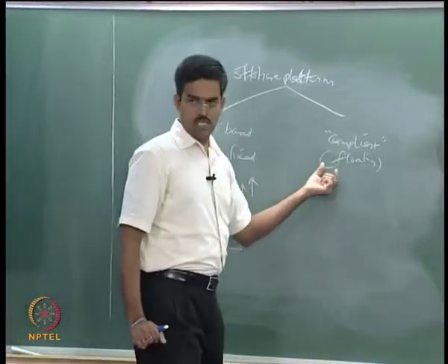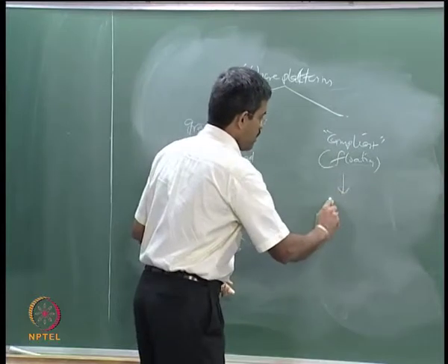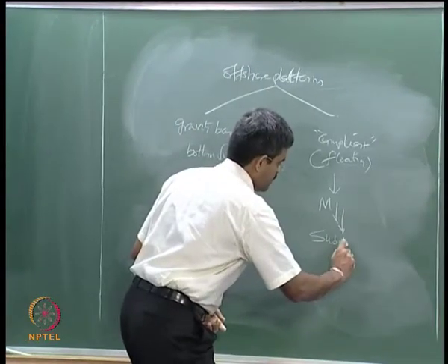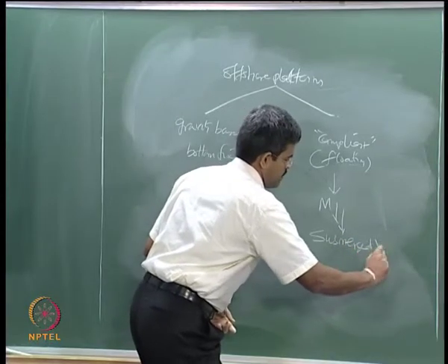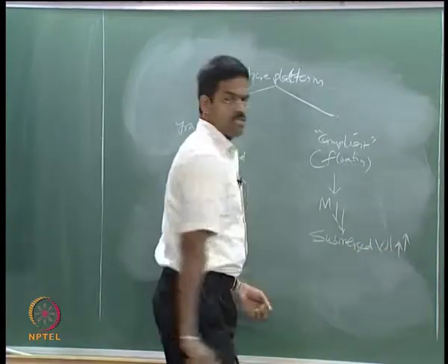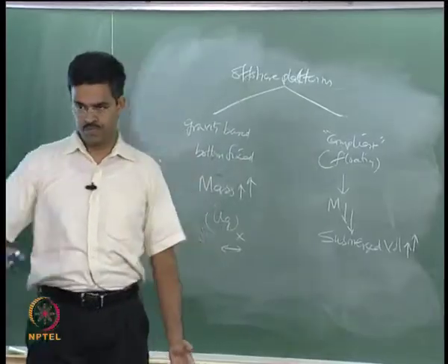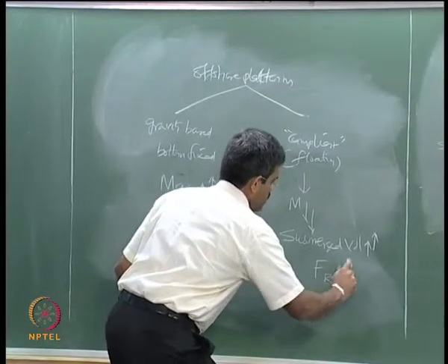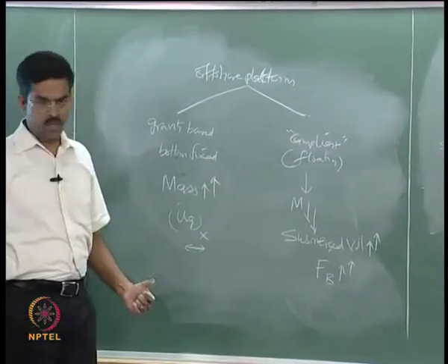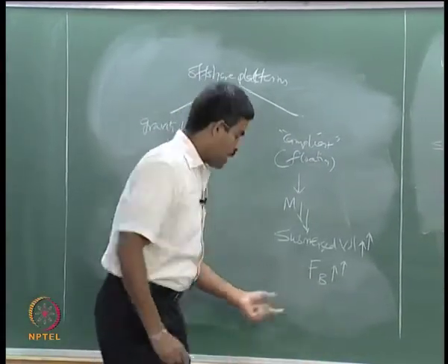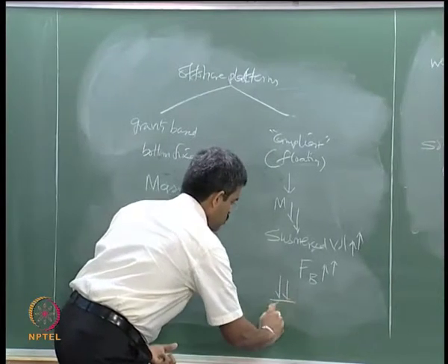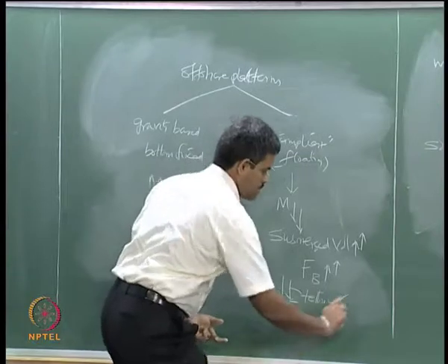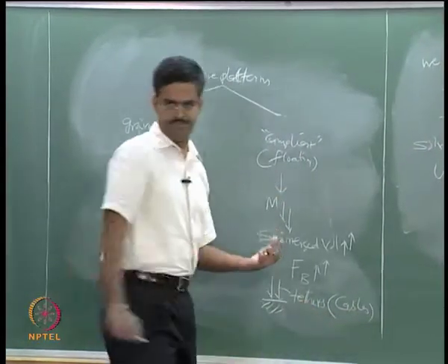If you look at the floating structure, very simple, the mass is very less, but the submerged volume is very high, because they are buoyancy dominated. Okay. The buoyancy domination in these platforms is generally very high. To counteract this buoyancy, I generally hold it down to my foundation using tethers or, in layman's language, cables.